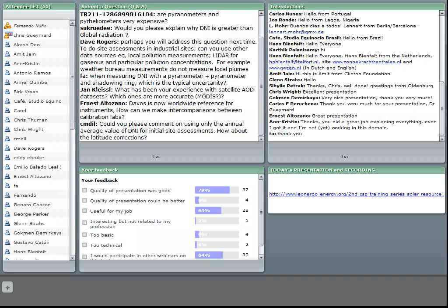If you see that your annual average DNI is 8 kilowatt hours per square meter per day, you should be in a safe place. If, on the contrary, it's only 2 kilowatt hours per day, then you might have a problem, and certainly not a good place for CSP. Now, I mentioned this story about the Kenya data that I found, where according to NREL we have a very good site for CSP, and according to DLR it's a very bad site. So which one do you believe? It's another issue around that question.